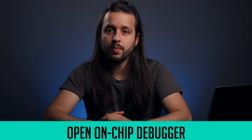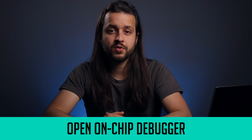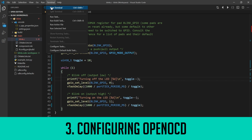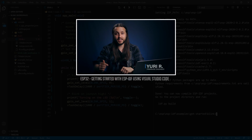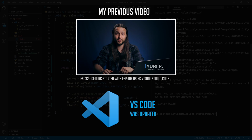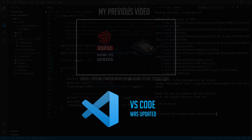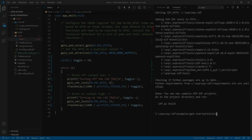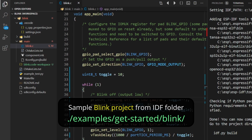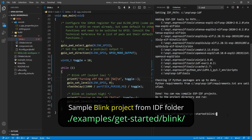OpenOCD stands for Open On-Chip Debugger and is responsible for managing the communication with the debugger driver, in our case, the FTDI driver. Let's open a new terminal on Visual Studio Code. Make sure your environment is already configured for the ESP-IDF. If you don't know how to do this, check my previous video here. By the way, as many of you pointed out in my last video, Visual Studio had an update and now we need to configure the IDF terminal in a different way. I will leave a link with the new instructions in the description. In this example, we are going to use the same Blink project as before, to keep things simple.